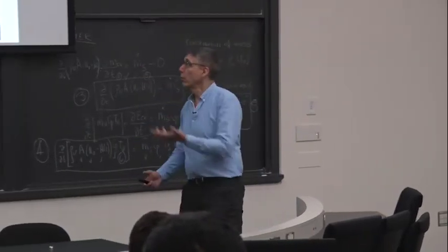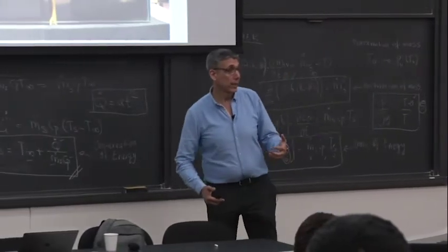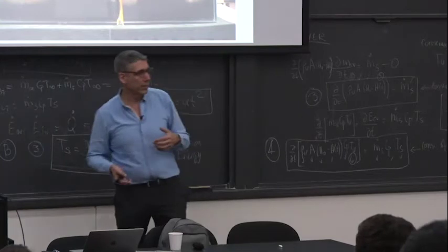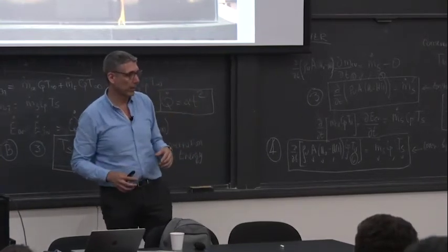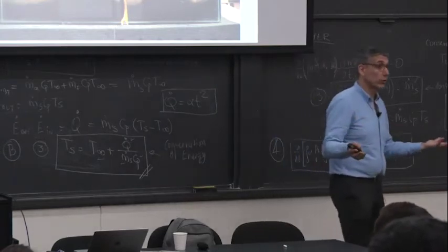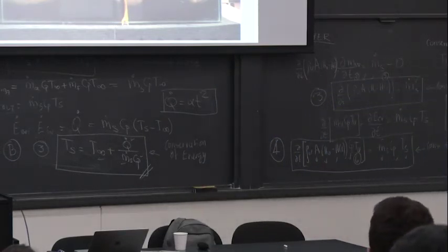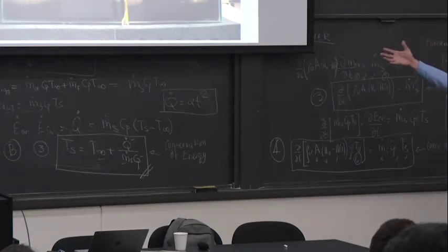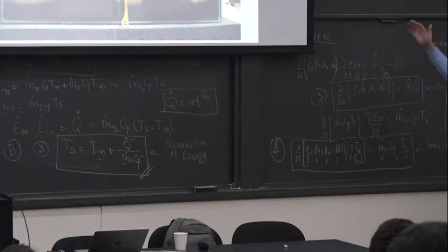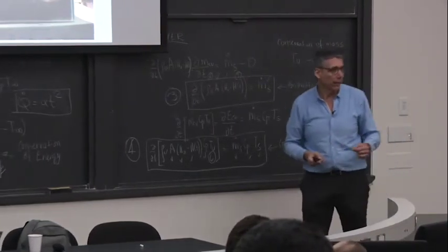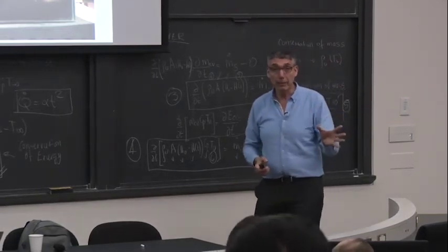Because the water has a very different density and viscosity than the air, I can play with the density gradient so that I maintain the non-dimensional parameters. So that's very well known. It's called saltwater modeling, and people do smoke analysis by using the same thing. You can put the model of a building inside the tank, and you inject a little bit of ink, and then you see how the smoke propagates and how it fills up the building. Is that all okay?